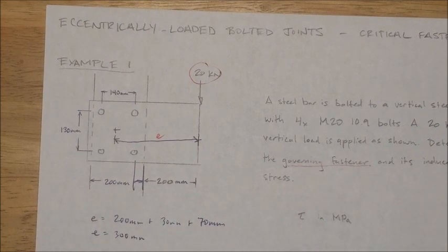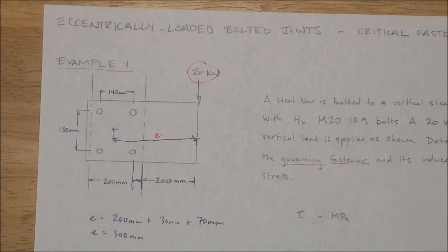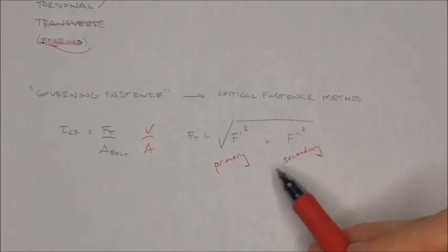So, things to take away. Always go slow in writing units. There's no sense in missing a problem here just for units. The eccentrically loaded bolt info in the reference manual is very difficult to use. The formulas are confusing. There's nothing near as simple as this formula.